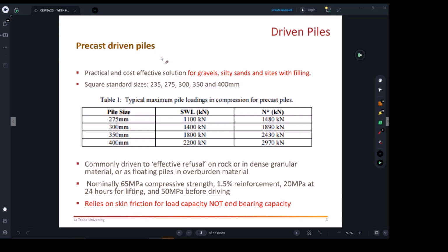Mostly we use this in constructing roads or constructing the piles below towers. You see most of the buildings in the city, before they start building the footing, they're going to be nailing down piles. These piles will basically be there to take axial loads. The piles that we talked about last week are basically for a retention system for retaining walls.